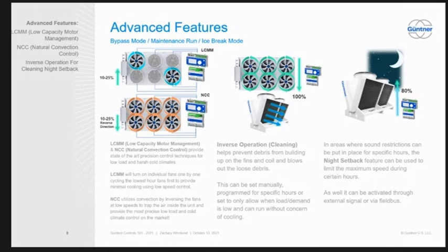Another thing that we do is we look at the fans' motor runtime. And when LCMM is turned on, we request the fan with the lowest runtime first, and then we go to the next lowest runtime, and so on and so forth, to extend the life of the motors. So that's a nice feature, especially for northern climates.